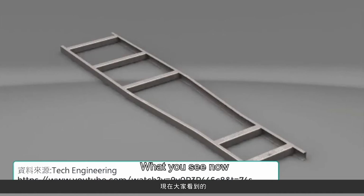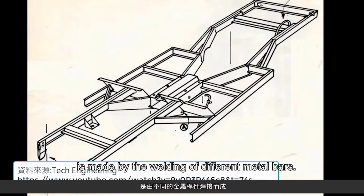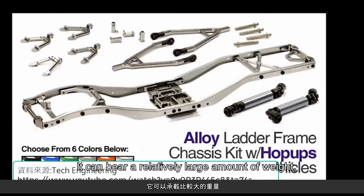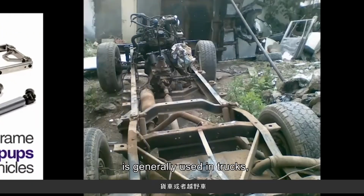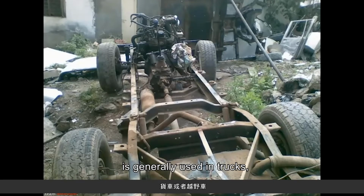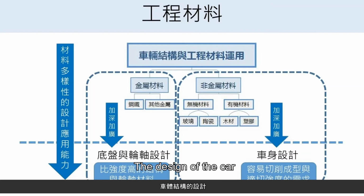What you see now is the ladder frame of the structure. The main structure of the ladder frame is made by the welding of different metal bars. It can bear a relatively large amount of weight, so this type of structural design is generally used in trucks, vans, or off-road vehicles. The design of the car body structure is closely related to the engineering materials used.